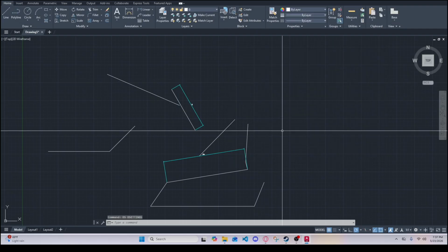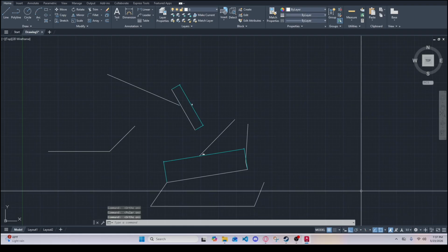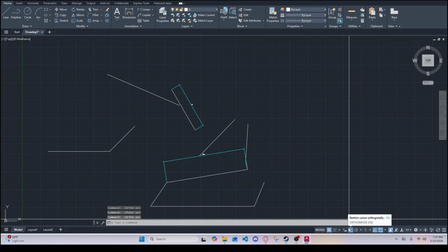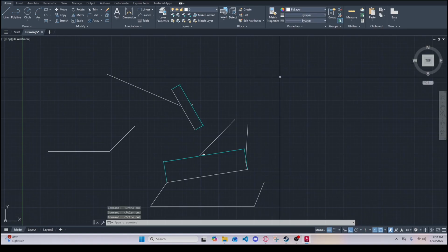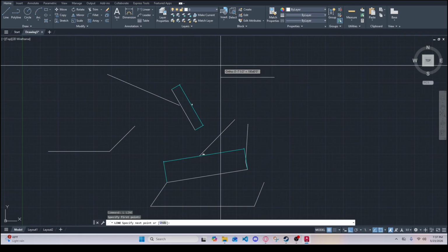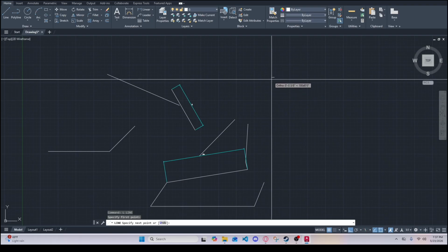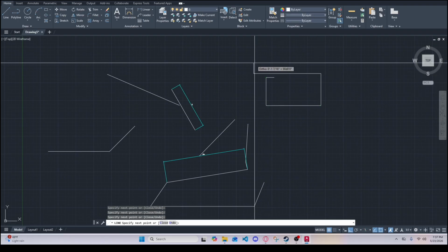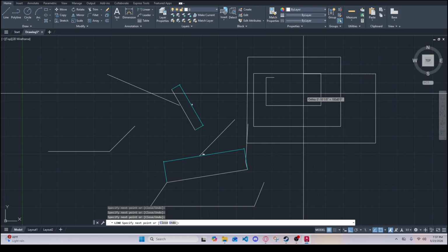Press OK. So right now, as you can come down here and hover over it, as you can see, when it's highlighted, it's on, and you can only choose between both of them at once. You can't have them both on or off. What's that showing? As you can see, this is your ortho mode, which is F8. So back to what I was explaining. If you go ahead and just type L and enter, or spacebar enter, as you can see, it's only giving me the option to go left, on your x-axis. That's what F8 does. So it gives you sharper, quicker ways to go about it like this, in order just to make 90-degree angles.